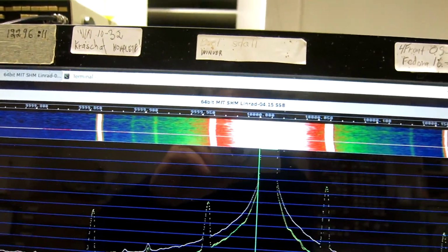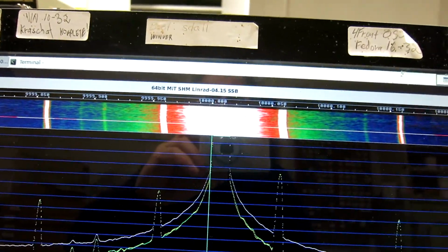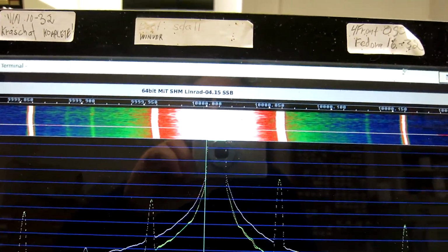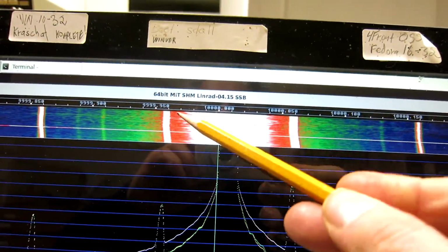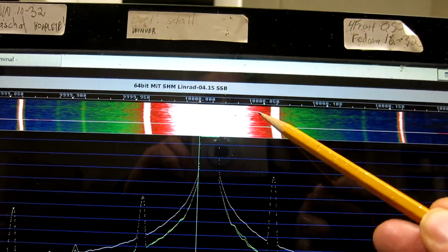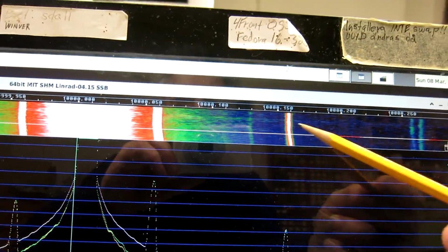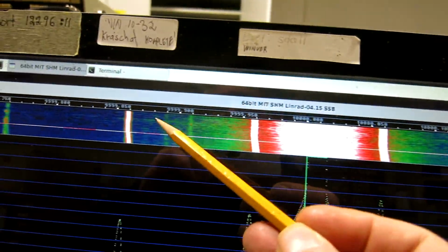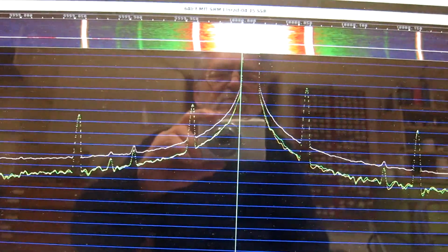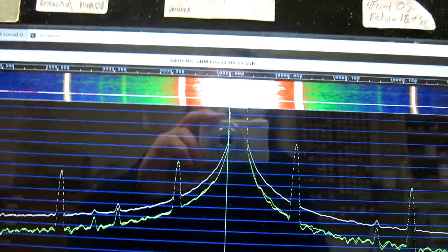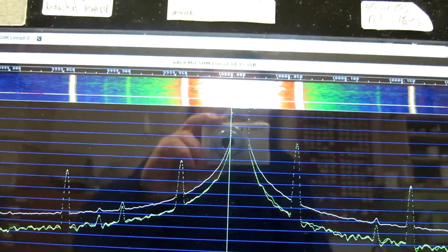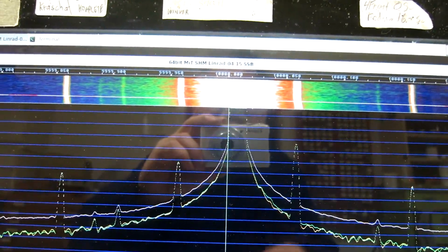Now with a higher power on the crystals, not much but a little higher, I see bursts of crystal noise now and then. Here is one, for example. You can see on both sides, and it stretches out here as well as here. And it was significantly worse just when I started it, but then the frequency stability was very poor because it was warming up.